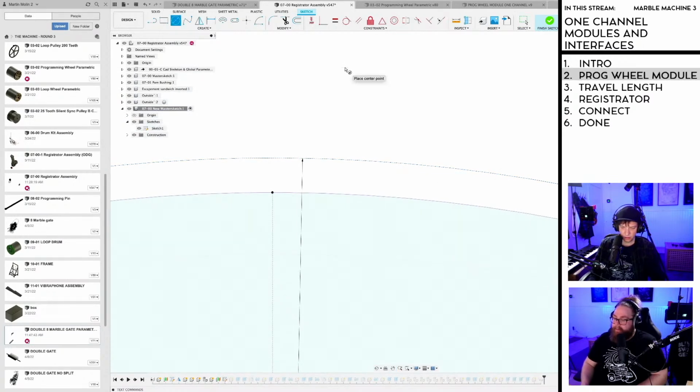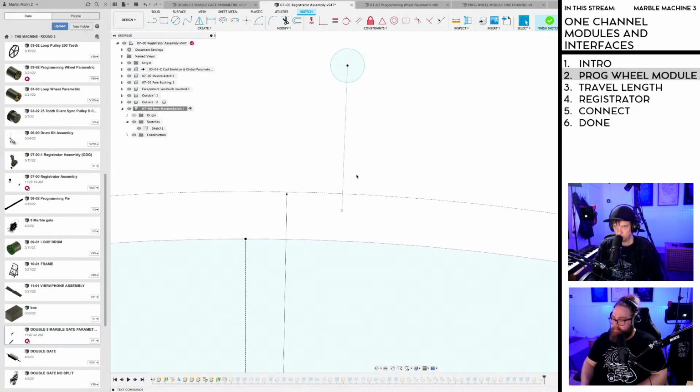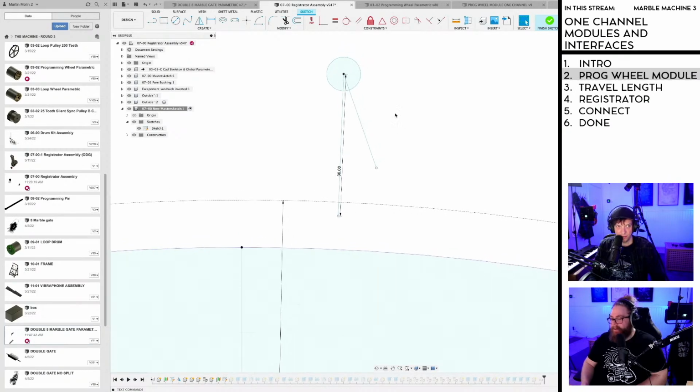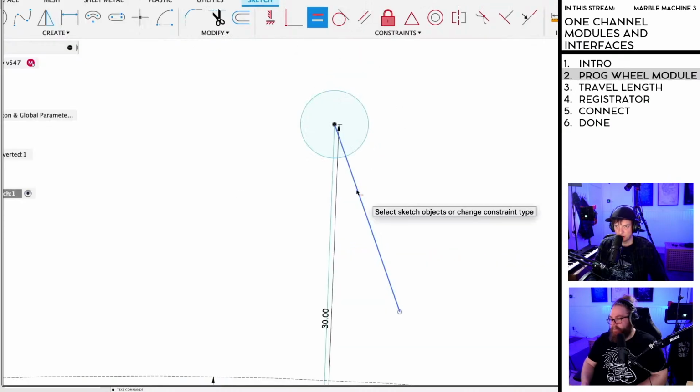And then we can show very clearly if we do a pivot point here and we go down below like this much. So we say that you are tangential with 30. And then we draw another line. We can use equal sign, which is a super nice constraint.